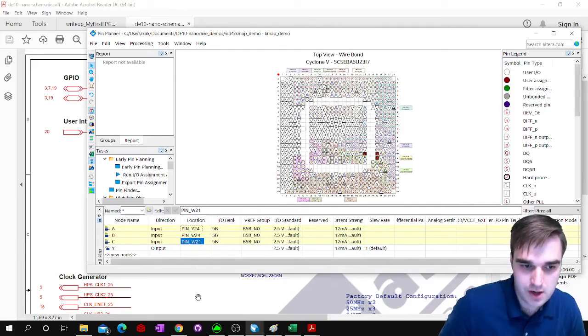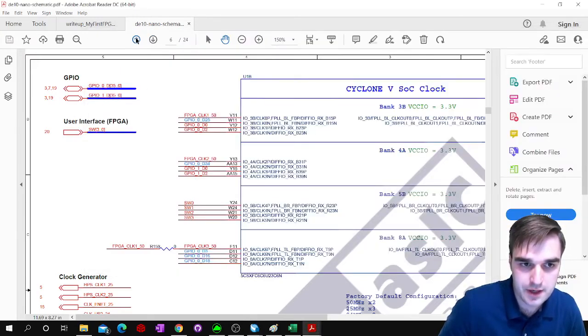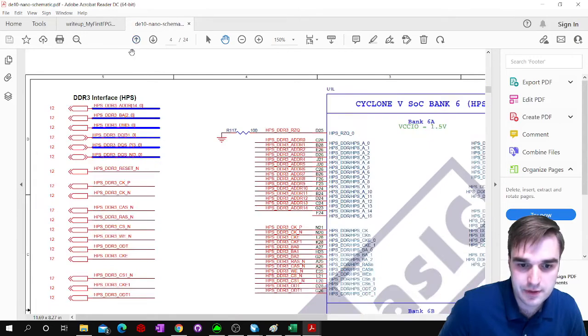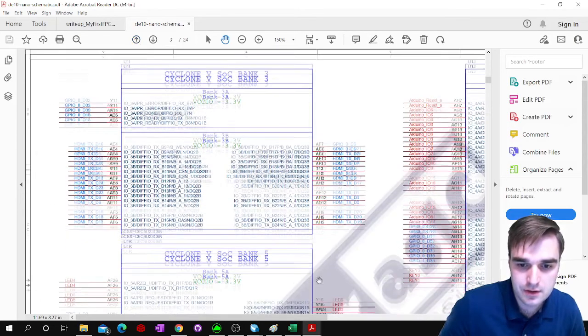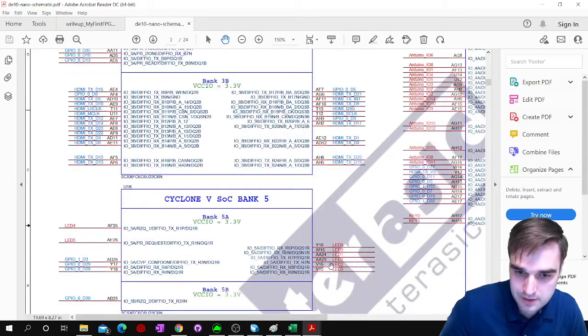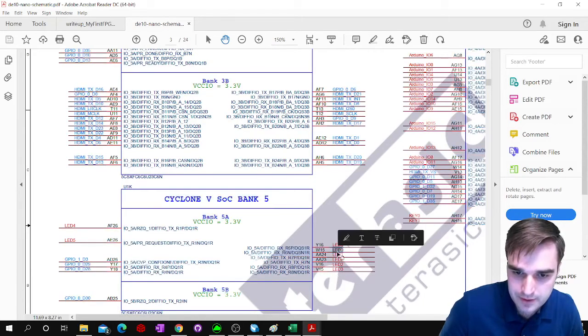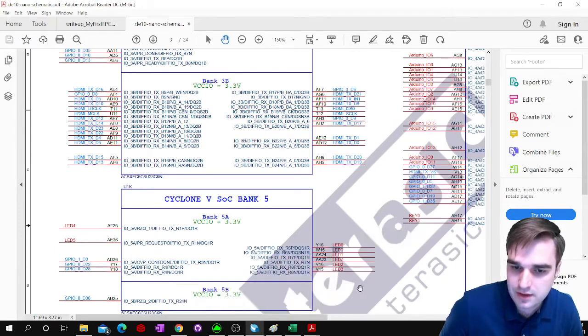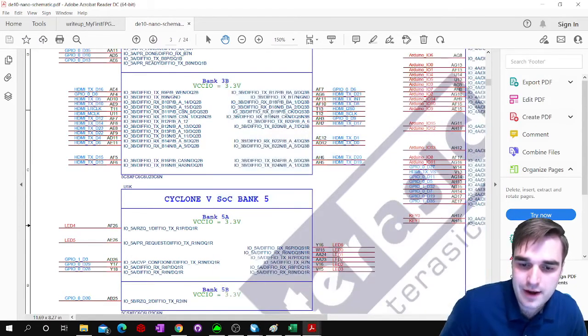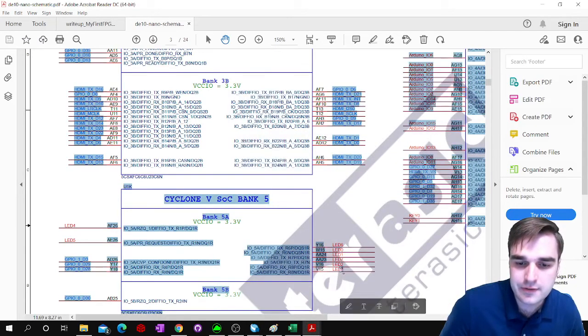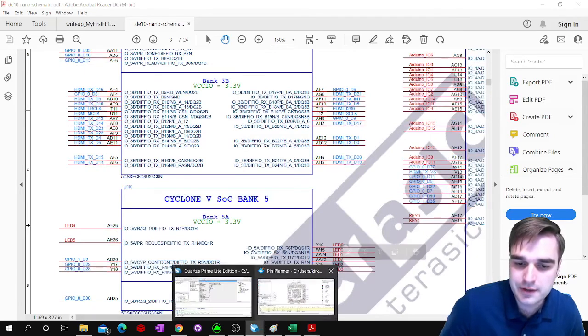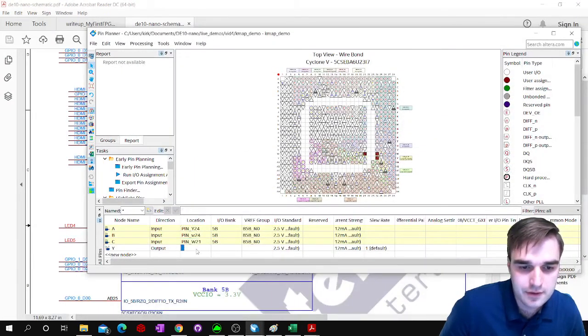And then lastly, our output. Our output is going to be on an LED, which I believe is on a previous page. I think it's, yeah, here it is. Okay, I'm getting used to these schematics now. Let's do W15, our good old friend, LED 0. Why not? Actually, LED 0 is probably tired by now. Let's do V16, LED 2. We don't want LED 0 to get too tired. So V16,